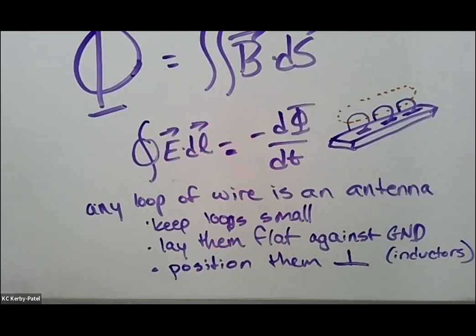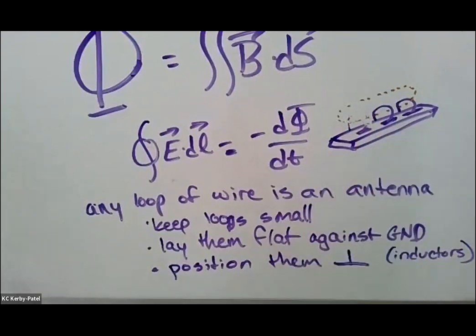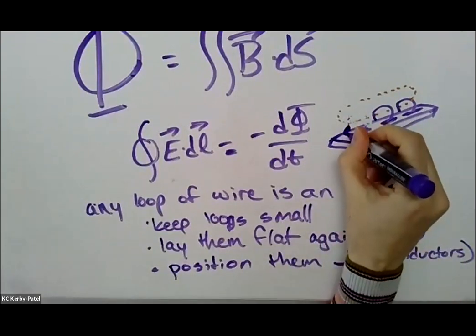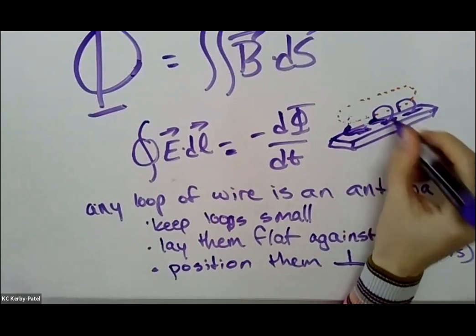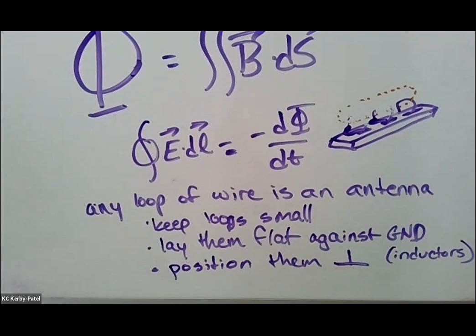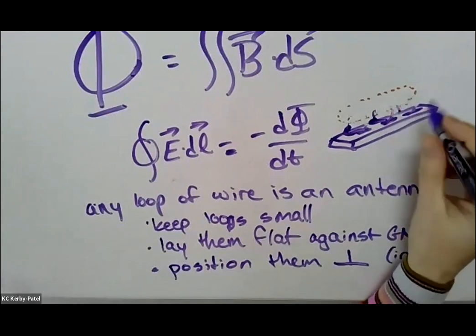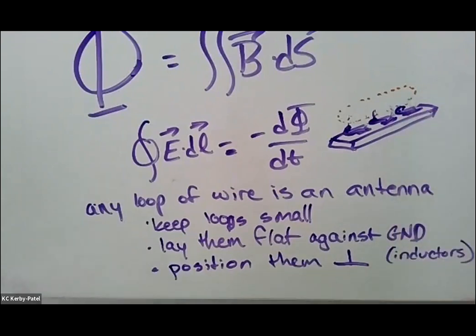This is really an important thing, and it really helps with circuit troubleshooting. When you have something where maybe you're measuring the circuit, but the signal just looks really noisy for some reason, just take these little loops and fold them down against the ground plane so they lay flat instead of standing up. Because then the area of the loop is so much smaller and not very much magnetic field can go through it. There's no field on the ground plane.